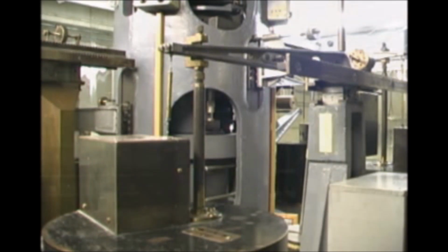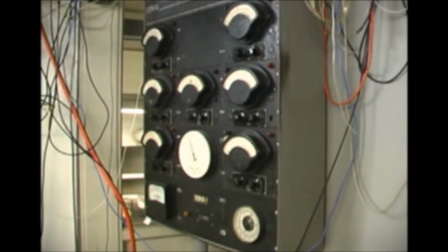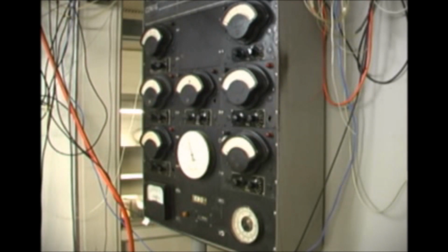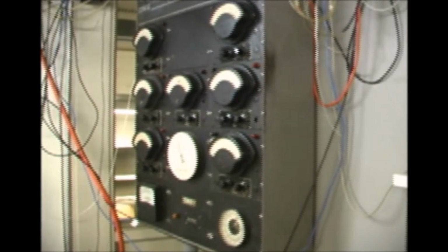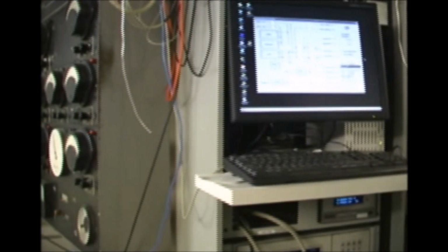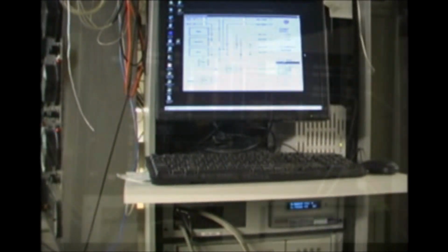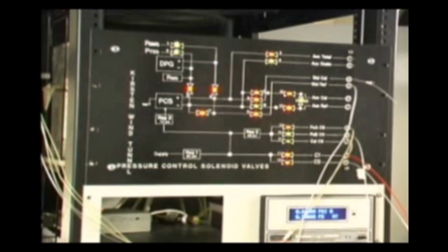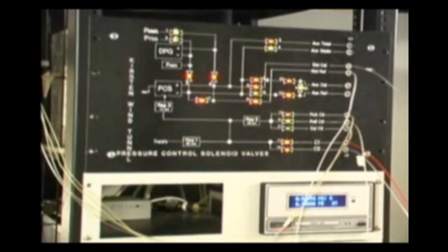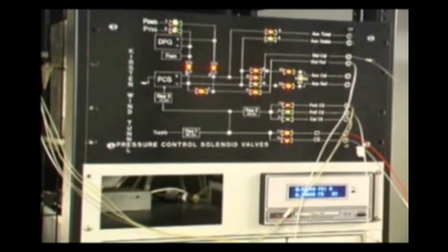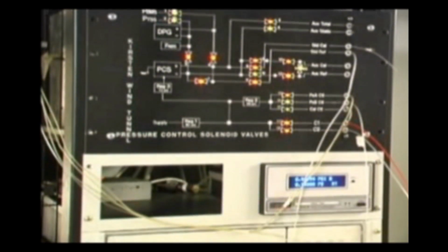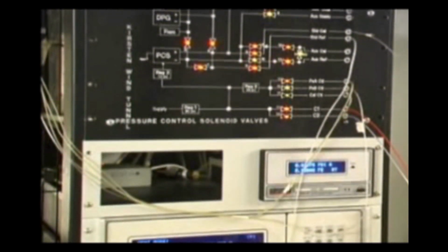The output voltages are then measured by our data acquisition computer and converted to engineering units of pounds and inch pounds, which are saved on the Kirsten wind tunnel computer network. The Kirsten wind tunnel is also capable of measuring pressure data. Pressure tubes can be routed to small holes on the surface of the model from an electronic pressure scanning system, or EPS, which monitors the individual pressures. The EPS has a capability of measuring up to 1,024 separate pressures simultaneously.